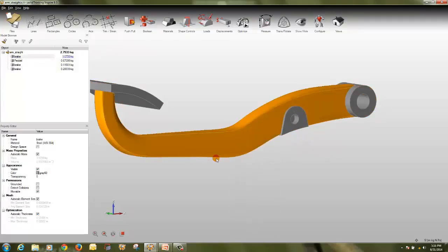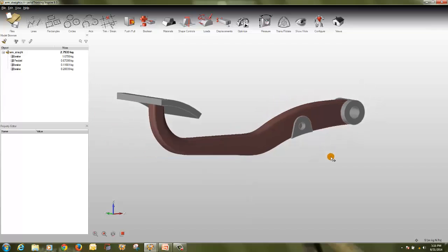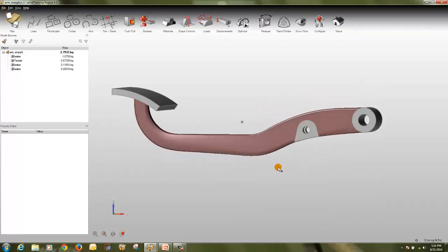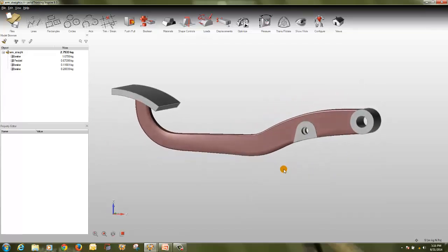So I will right click and make this design. So in this way you can edit a CAD geometry to make it in a design and non-design space. So whatever CAD geometry you have, once you import it, it may occur that it comes in one part or multiple parts. So if you want to make a certain sections of design and non-design, you can use these commands